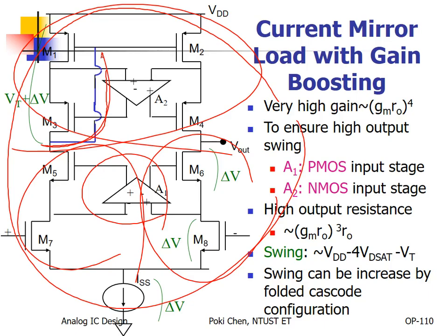Usually, for the first simulation, you will see cutoff, triode region. It is really hard to make all the transistors in saturation region. You need to face the challenge. And even though you make it finally, you still need to pay for very, very high power consumption.